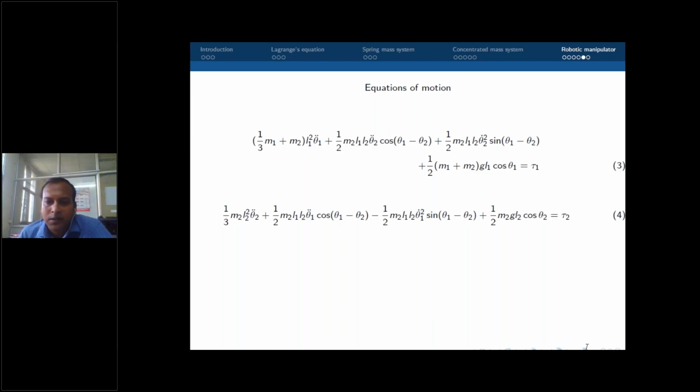Sensor is just like a mass. So in the manipulator, this is a mass, and you consider the mass. If the sensor's mass is very high compared to the manipulator mass, then the moment of inertia of that rod will change. But if the sensor's mass is small compared to the mass of the manipulator, then we need not consider that. It is a negligible thing.